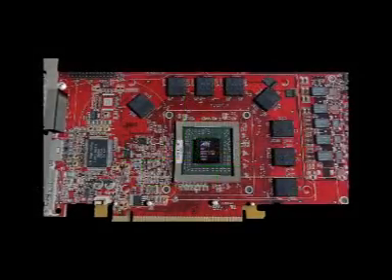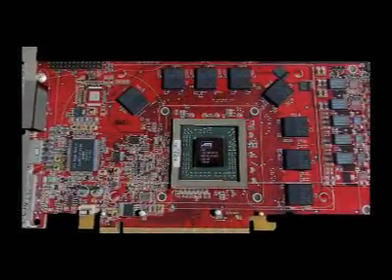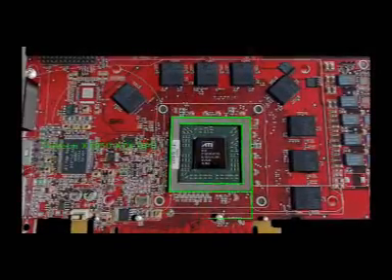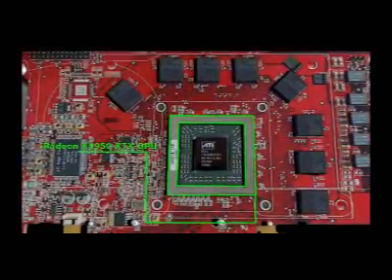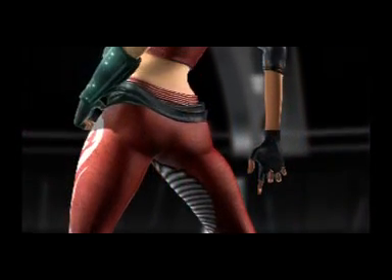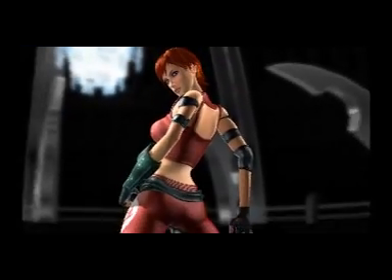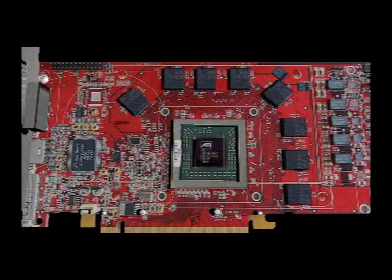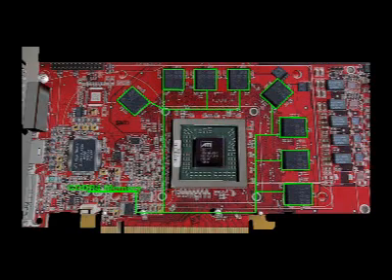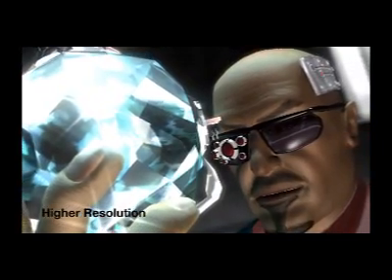The board shows off several notable components. First, there's the ATI Radeon X1950 XTX GPU, a 90nm chip leveraging 384 million transistors in a 48 shader architecture. In other words, the chip features a lot of programmable logic used to generate the most realistic on-screen effects possible. AMD packs the card with 512 megabytes of GDDR4 memory, an industry first, running at an effective speed of 2 GHz to the processing core.